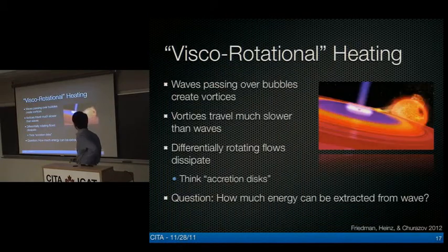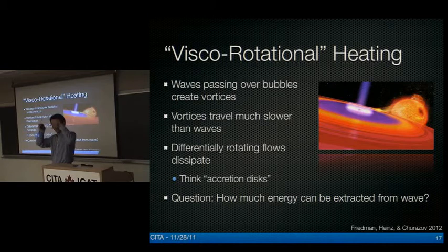Okay. So what are we left with? We have this vortex ring, right? The velocity of this vortex is roughly a quarter of the difference in velocity posed in free shock, right? The velocity jump across the shock. That's the characteristic velocity of the problem. But it cannot rotate at this speed out to infinity. The velocity must drop fairly quickly. So we have a differentially rotating flow.